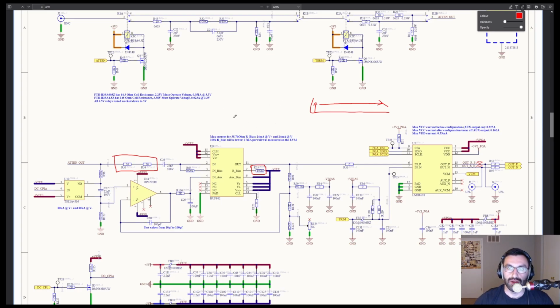But then you have a different way of doing it, which is to use a wideband noise source. So you basically, in the frequency domain, that's frequency, and then that's amplitude, dB. So you basically have a wideband noise source, which gives you a consistent amount of power at each frequency, and that way you can just take an FFT of it and see your response at a glance.